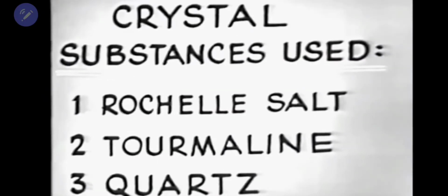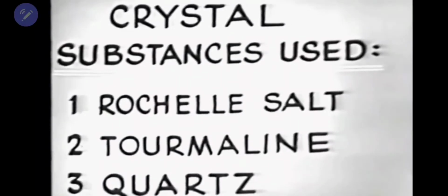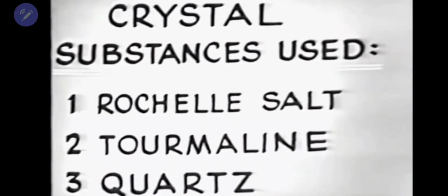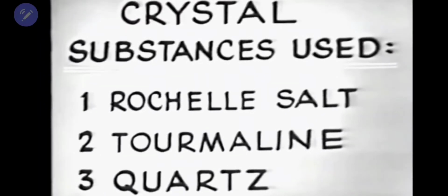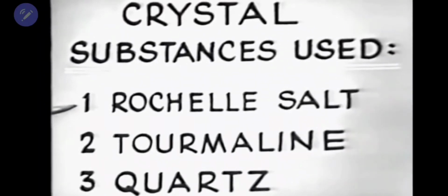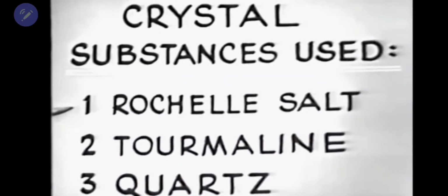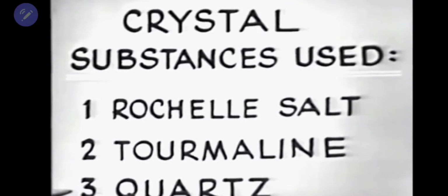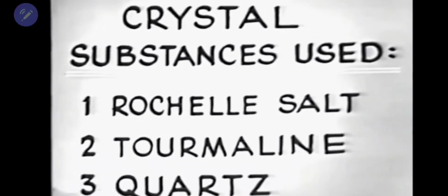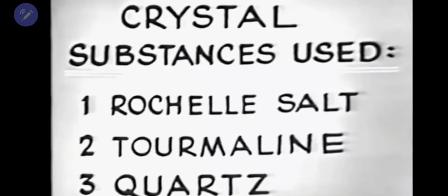Now, let's look at some of the crystal substances that possess the piezoelectric characteristics. They are Rochelle salt, tourmaline, and quartz. Of these three, Rochelle salt exhibits the piezoelectric effect to the greatest degree. However, quartz crystal is most generally used because it has a greater mechanical strength. Quartz crystal, remember, has a greater mechanical strength.